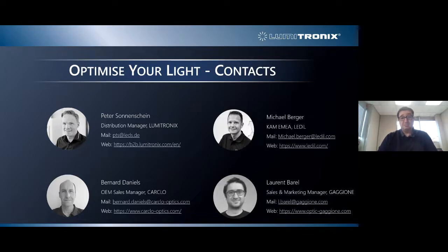It will depend on the application. Sometimes we will consider the 10% equivalent beam angle, which is exactly what we are doing to compute the CCI result. But for some other, more demanding applications, for example high-end shop lighting, customers will be mostly focusing on the 50% beam angle.